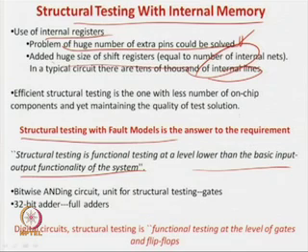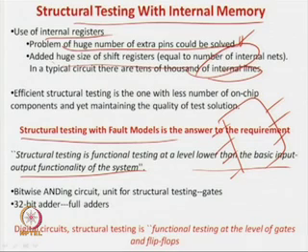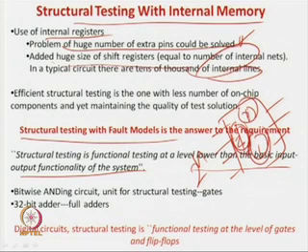That means, if you have a circuit like this and you want to do functional testing, then you have to verify whether all 2 to the power n inputs are verified. But if you are going for structural testing, then you can break up your circuit into individual blocks, and you just test whether these blocks are individually correct or not. Inside these we are not bothered.